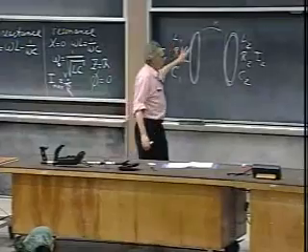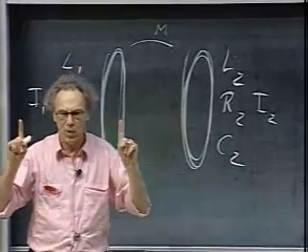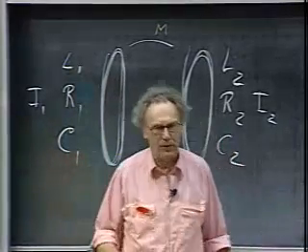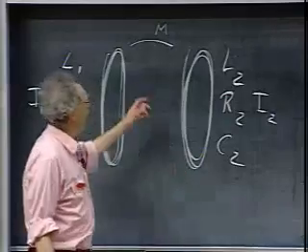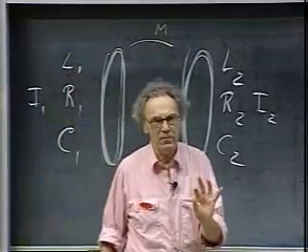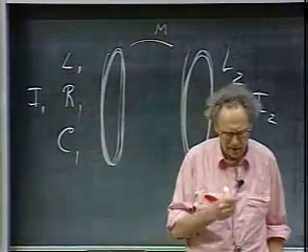In any case, what is important to know is that clearly, since you have two coils, you get two resonance frequencies. Not just one, but you have two resonance frequencies. And at least one of those resonance frequencies depends very strongly on the mutual inductance. And so the system is tuned to set at one of these two resonance frequencies.